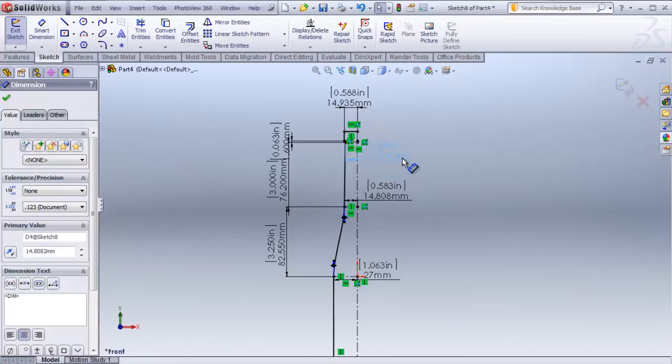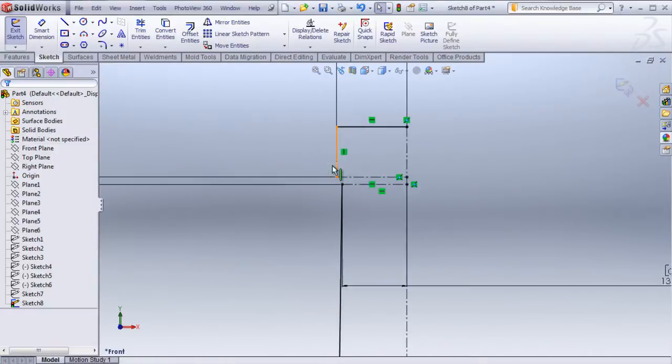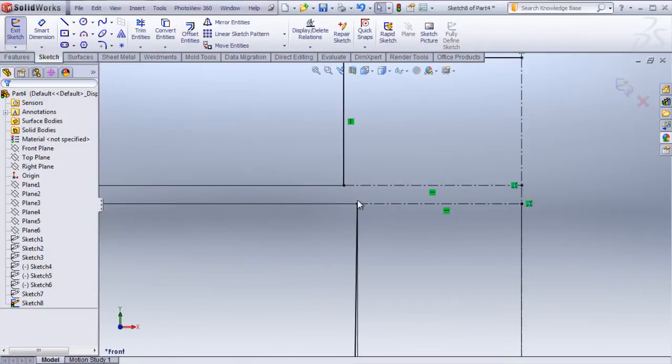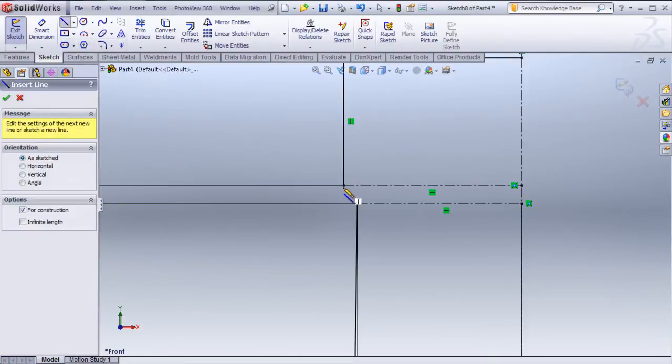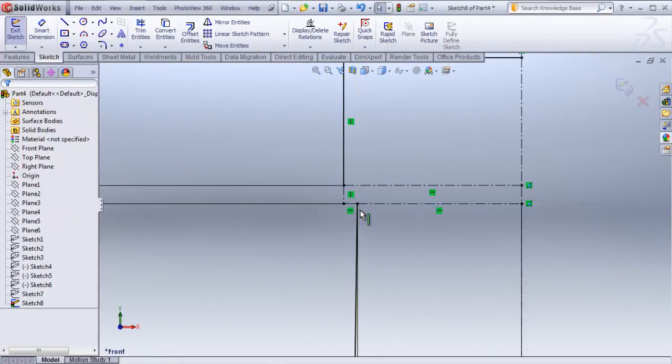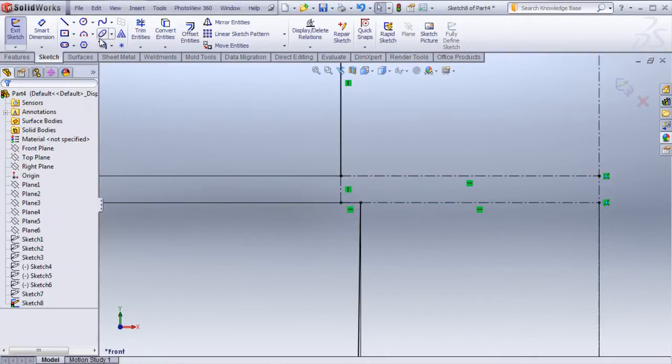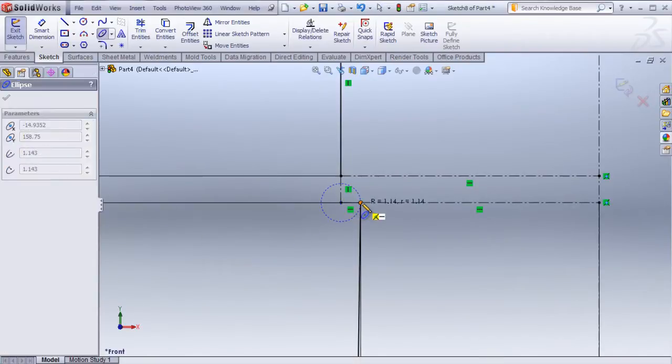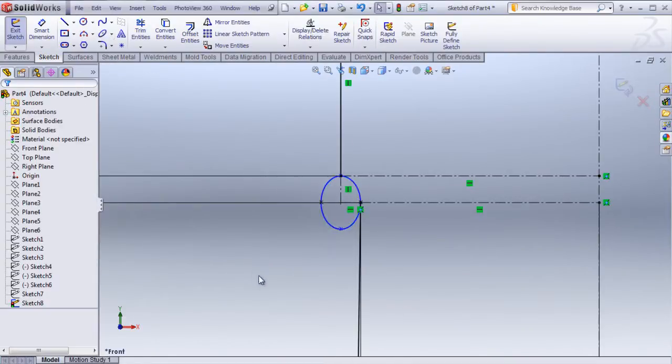Now what we really need to do here, because every little detail is figured out, is to connect these two joints. To connect those two joints, I am going to develop a center line which will go straight up to here, and then it connects here. So these are center lines. And then finally, I'm going to develop an ellipse right here, starting from this point. This is the smaller radius, this is the bigger radius. Perfect, I got that going.